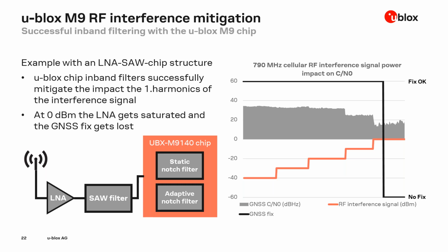This is quite an important measure you can take also to verify if there is a problem. We will see later on in the video we prepared that this will change, and this gives quite a good indication if there is RF interference present. You see it's about a level of 35 dB-Hz for quite a few steps of increased power in RF interference.